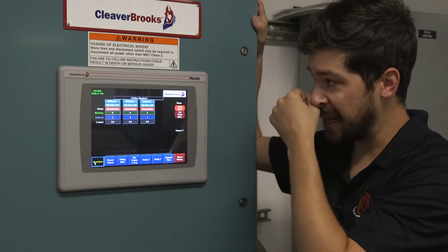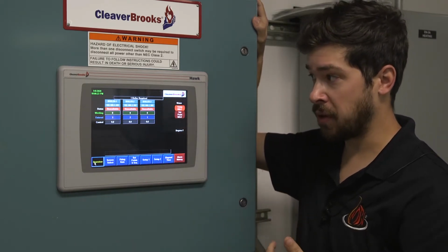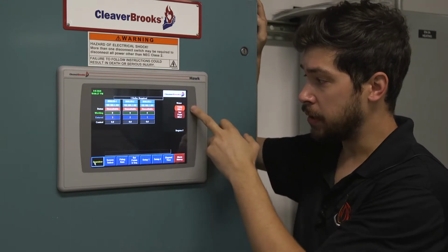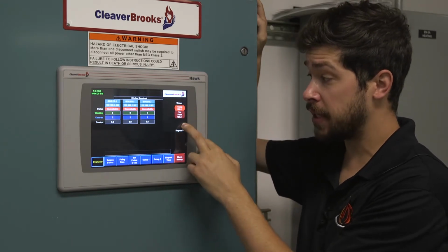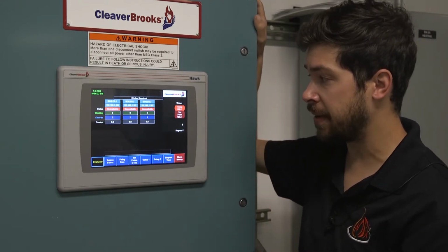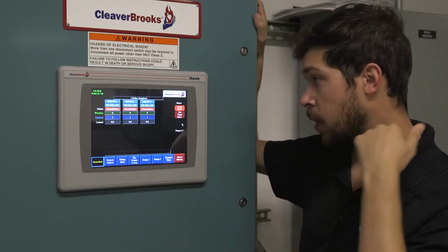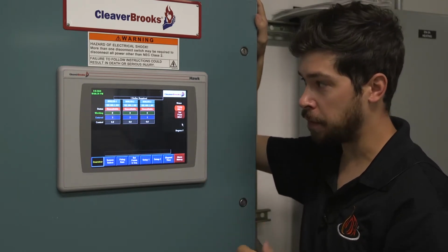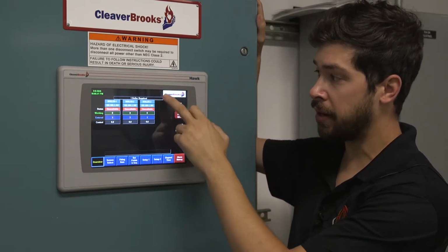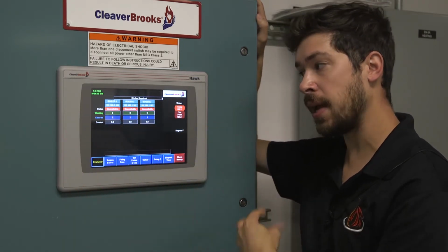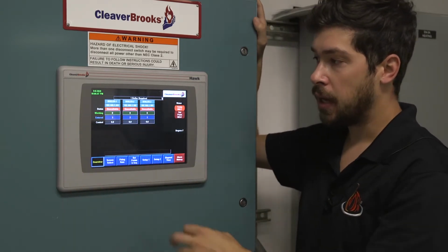Up at the top it says one boiler is required. Right now that's just looking at water. This is the set point for the system as it's been set, and then the current temperature as we see it, which was shut off as we were ramping up and didn't hit our off point. So it's still saying one boiler required. Sometimes it would say 2 boilers required. All depends on what it wants to see for the load.